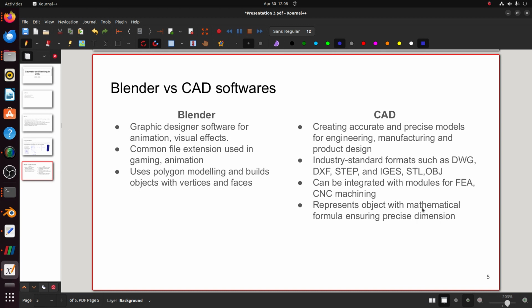So let's say the inlet was created by taking the difference between some geometry and the cylinder that you had. In that cylinder that I was using for creating the difference, if I had more points to define the surface, the inlet also becomes much finer. And if the inlet has many more vertices, does that mean that when I use snappyHexMesh on it, it becomes very fine? Yes, sir, it can do that. So the number of points on the cylinder while taking the difference is connected to the final snappyHexMesh fine mesh.